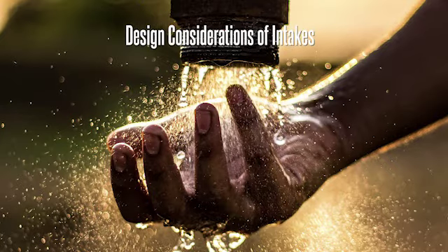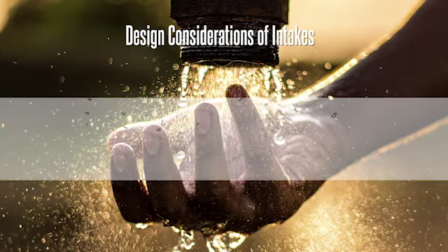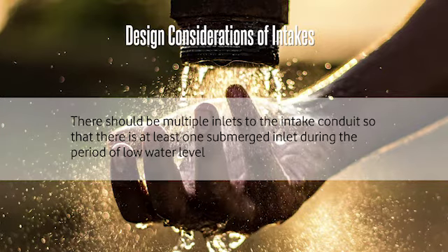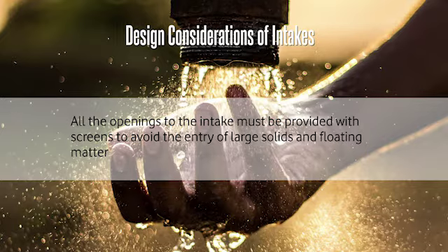Design considerations of the intake. There should be multiple inlets to the intake conduit so that there is at least one submerged inlet during the period of low water level. All the openings to the inlet must be provided with screens to avoid the entry of large solids and floating matter.